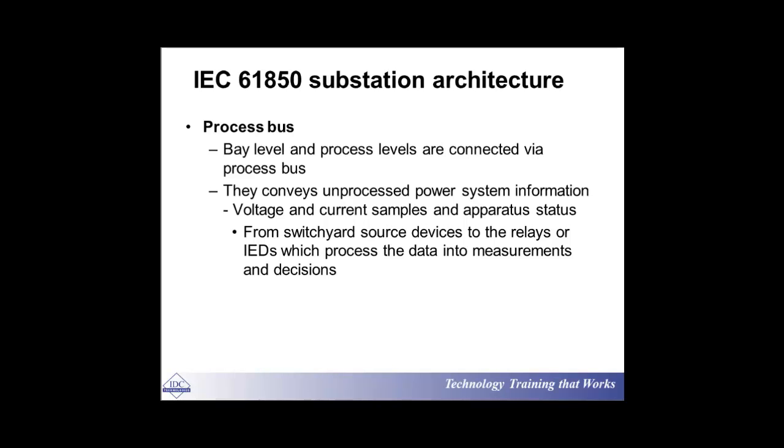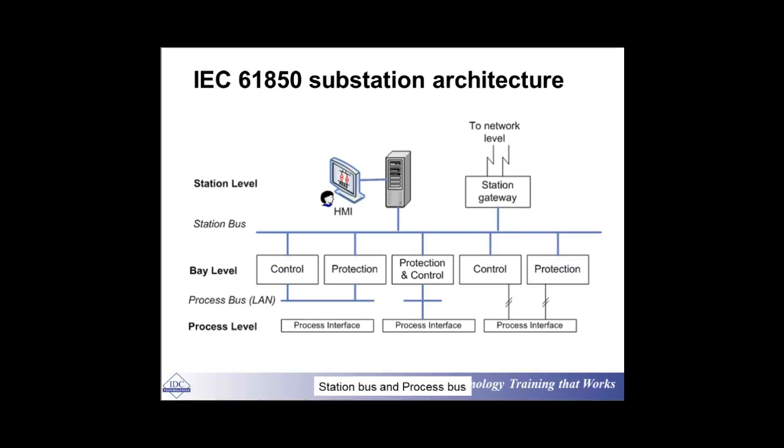On many occasions, the operator, the designer, the engineer needs to know the status of this switch. Is it already open? Is it already closed? So they can define a logic, so that later on they say, if it is closed, do this; if it is open, do that. So that is the idea for this 61850. So we have to define a number of logics.